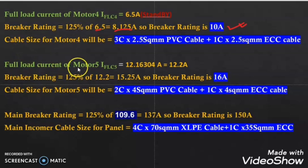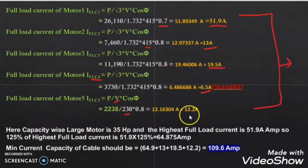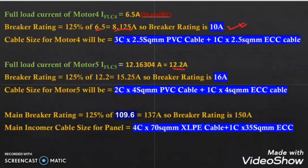Now the full load current rating for motor 5 is 12.2 ampere, which we calculated here. So the breaker rating will be 125% of 12.2 ampere, which came as 15.25 ampere. So the next available standard breaker rating is 16 ampere.